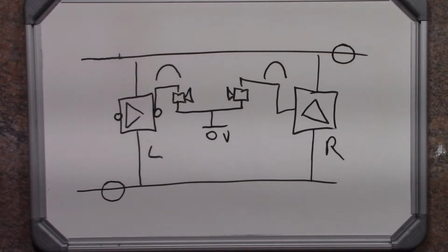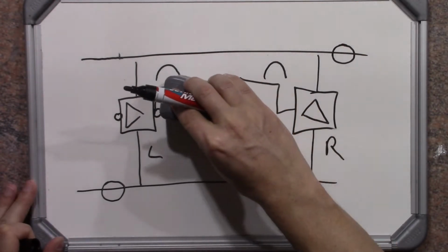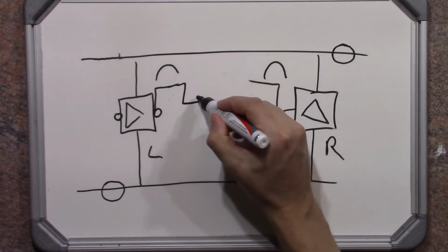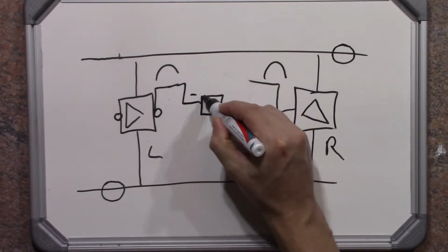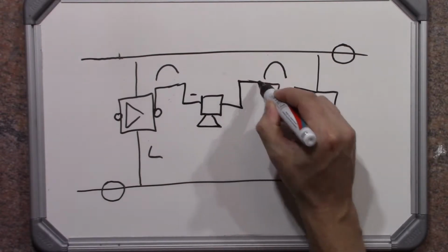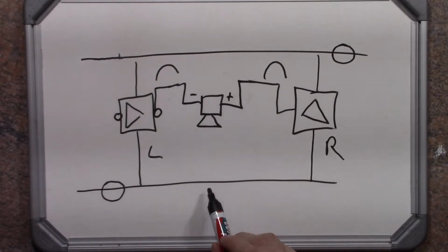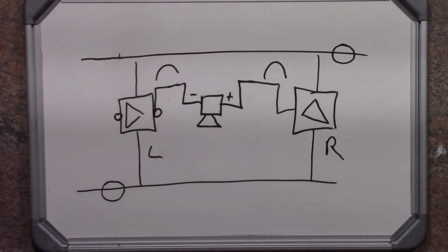This also enables the amplifier to be used in bridge mode. It simply means you can use the negative output of this amplifier on a speaker and then the positive output of this amplifier, and that will in reality make your amplifier 4 times stronger. This of course can put a lot of stress on the transistors, and I wouldn't recommend going to impedance lower than 8 ohm on this specific design.